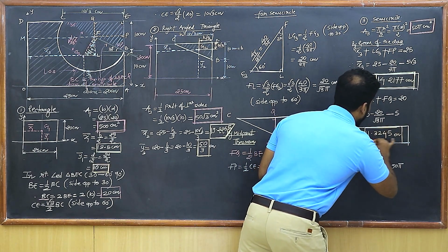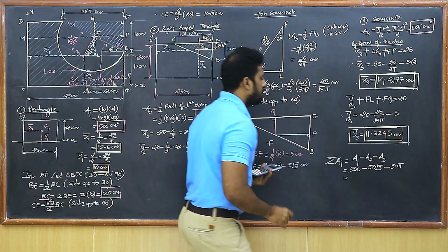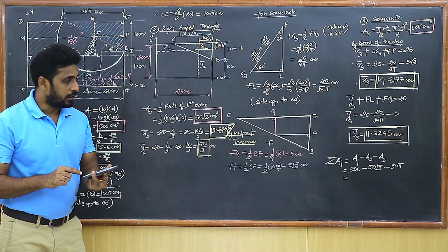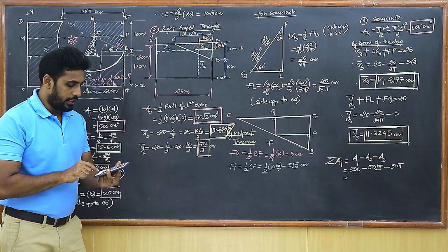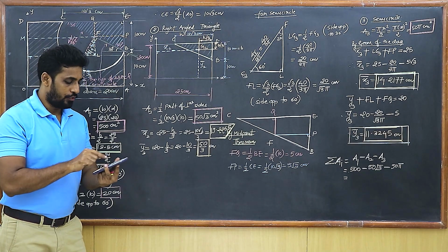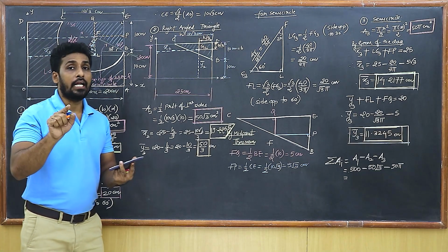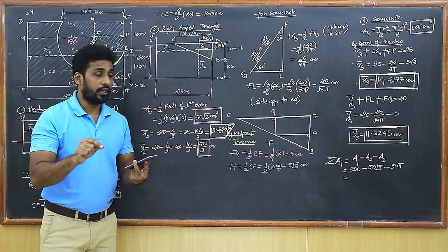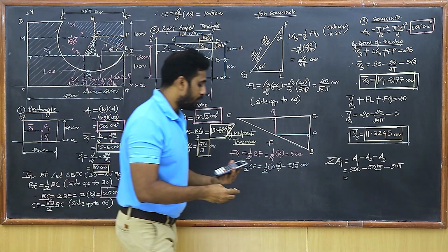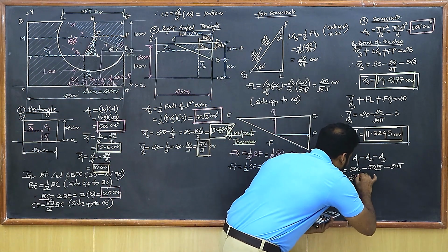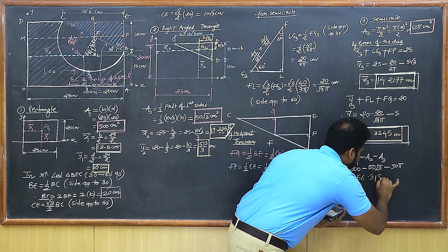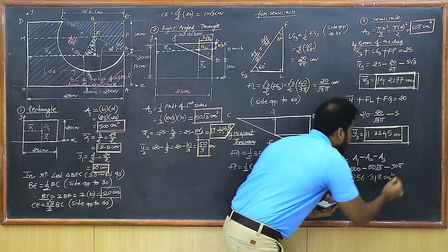So I've got a value of Y3 bar, and I also want to find summation of AI. So let's get summation of AI. It is going to be 500, isn't it? Then minus of 50 root 3, the second value, and then minus of 50 pi. You need to do your calculations on your own. Don't just keep on copying the calculations. It is going to be 256.3178. So I'm going to write my answer as 256.3178, taken as 8 centimeters square.